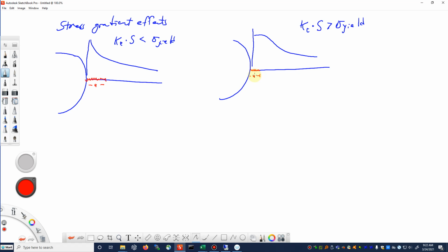And it also, like I said, depends on the load level. If you're on the right side of the SN curve where you're near the endurance limit, then probably stronger materials are better. And if you're on the left side, probably more ductile materials are a little bit better. And in most cases, you can't have both things.